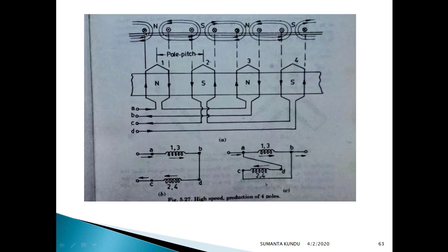So the interesting thing is that this is downward, north pole, right? North pole. So what happened? As these two become the same dot current, the number of poles is reduced by half. That is why it is a 2:1 ratio. So here the current is upward, this is the south pole, and in this fashion only 4 poles have been produced.